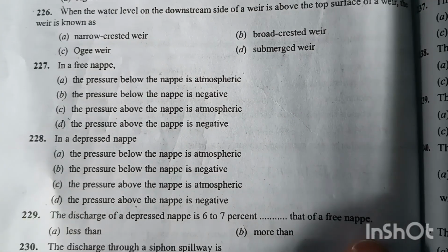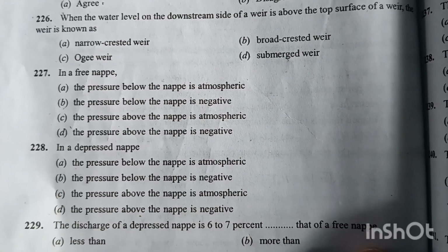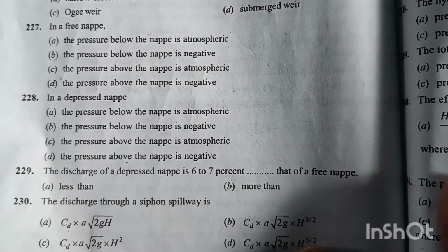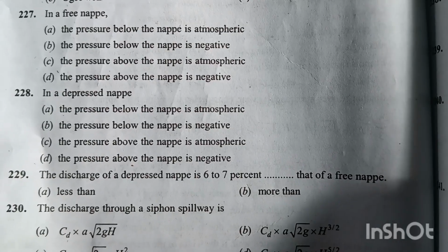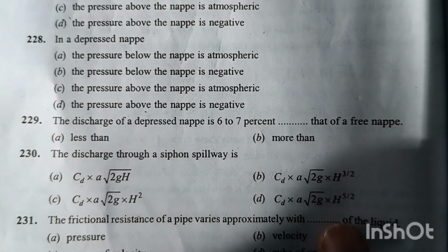Question number 228. In a depressed nappe, the pressure below the nappe is negative. Option B is the right answer. Question number 229. The discharge of a depressed nappe is 6 to 7% more than that of a free nappe. Option B is the right answer. Question number 230. The discharge through a siphon spillway is: